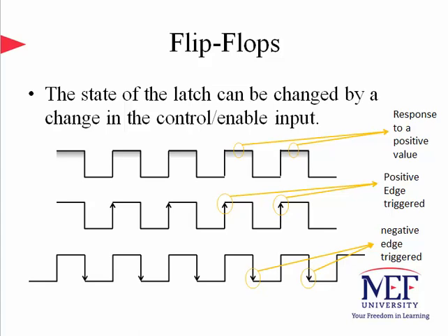Flip-flops are storage elements controlled by a clock transition instead of signal levels. Therefore, flip-flops are triggered only during a signal transition. Flip-flops are constructed such that they operate using a common clock of the system, and they respond to inputs only at clock transitions. In a latch, as long as the clock, or the control signal in our case, is positive, the circuit is responsive. That's usually a very long time for fast hardware. The key feature of flip-flops is the trigger effect, only at signal transitions.